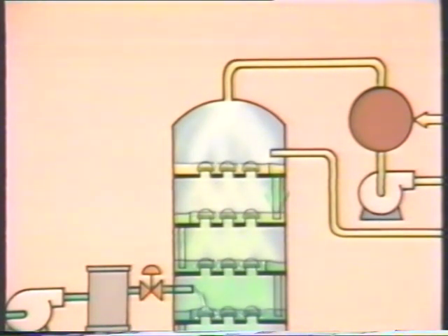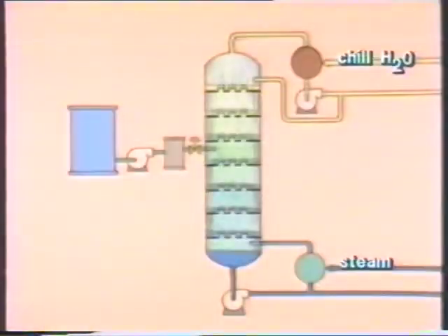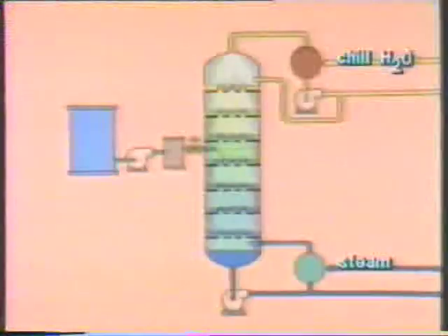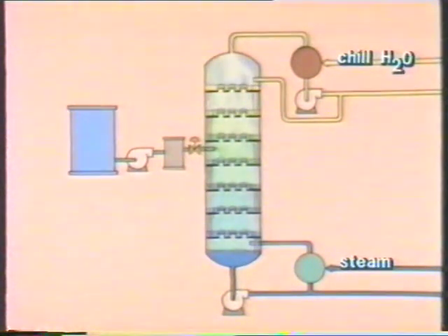The heavier part of the reflux itself flows down the tower while any lighter part vaporizes and comes back off the top. The process of refluxing helps make the overhead product purer because it helps prevent the overhead product from containing any heavier bottoms product.